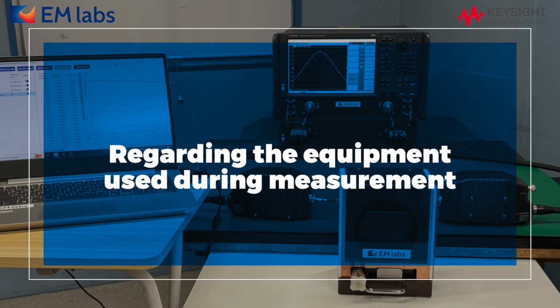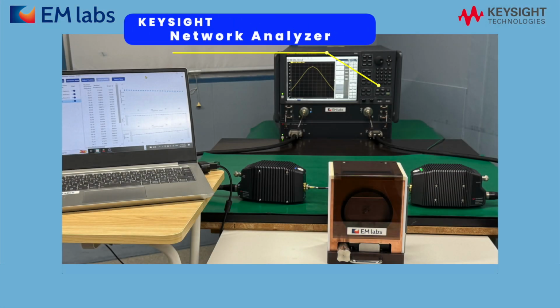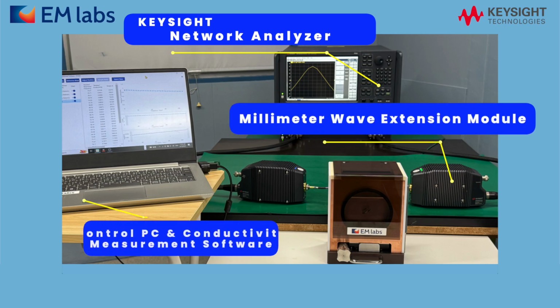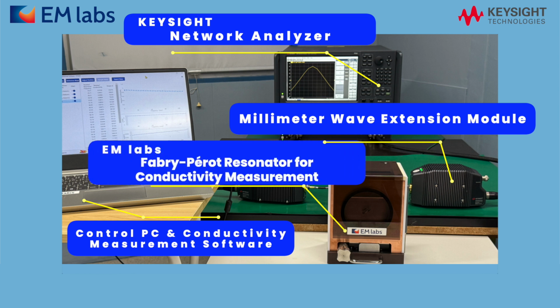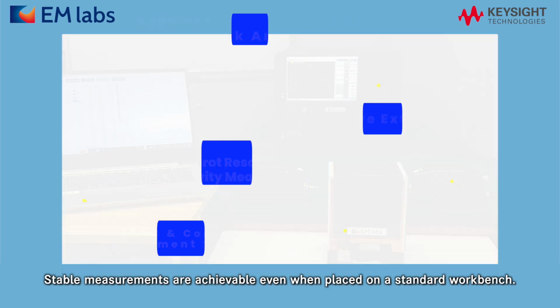Let us first explain the equipment used for measurement. Keysight Network Analyzer, Extension Modules, Control PC and Conductivity Measurement Software. EMlabs Fabry-Perot Resonator for conductivity measurement. This is the basic setup. Stable measurements can be performed even when placed on an ordinary workbench.